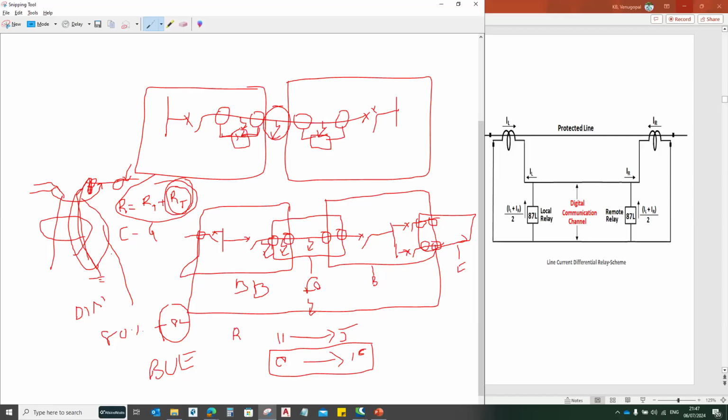But sir, they do not provide the distance, right? Backup earth fault does not provide the distance information, but since these kinds of faults can be sensed by backup earth fault as fast as, compared to the distance relays. Because in distance relays, the sensitivity to this high resistance fault will be very less because of these additional resistors. Okay, sir. Understood.